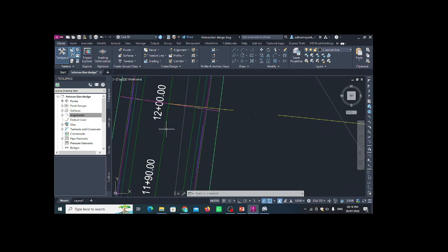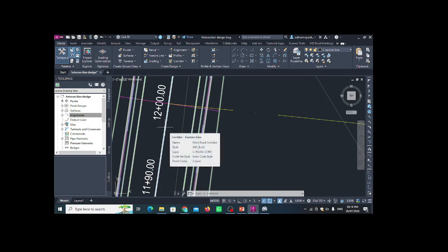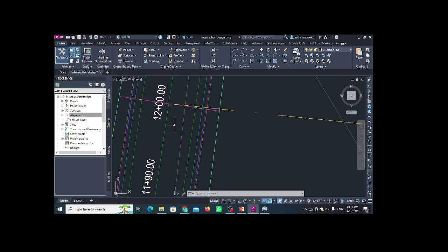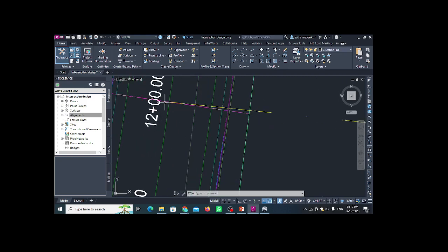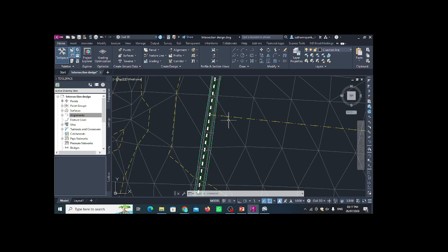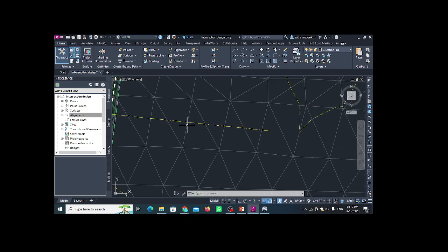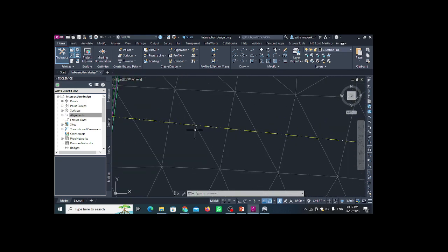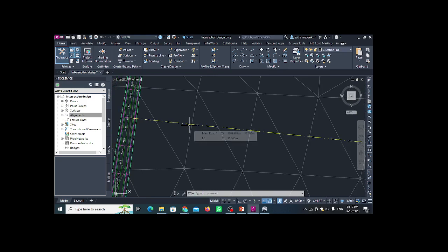You can see the point code is a crown. So crown is the center of this polyline. So for the center, we set one secondary road here. Okay, so this is just a polyline right now. To create the new road, you have to select this polyline.